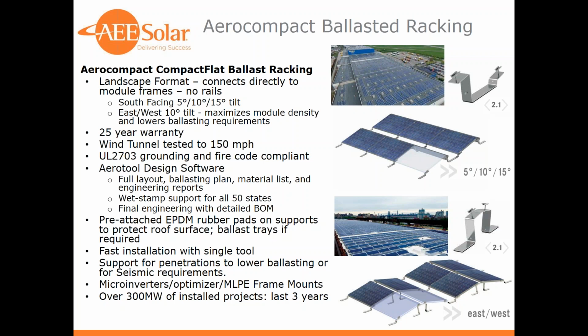So there's pre-attached rubber pads on the supports. There's separate pads that you place under the ballasting trays where needed. There's a single tool that's used to assemble the racking, and we have support for penetrations. Again, like we mentioned, we can lower the ballasting or we can add them for seismic requirements.